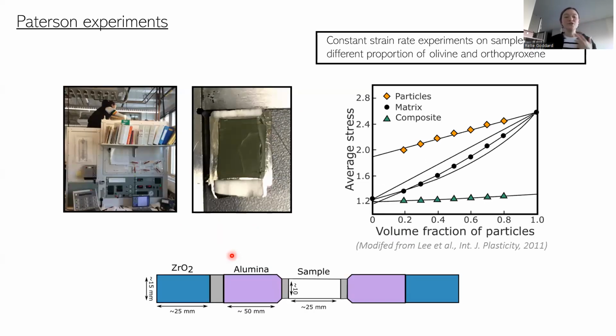And to do this, we use a different piece of apparatus known as a Paterson apparatus. It is a gas medium apparatus that goes to about 300 MPa. You can see me screwing in the top of one of them here. They have to be contained within these blast containers because they can essentially blow up. So slightly dangerous, but great fun.